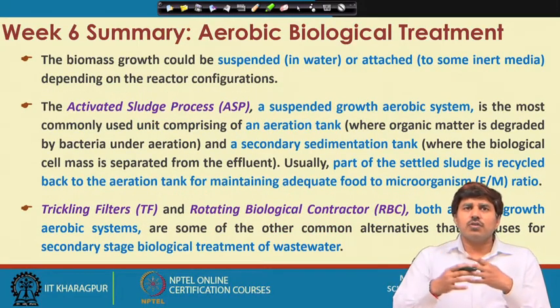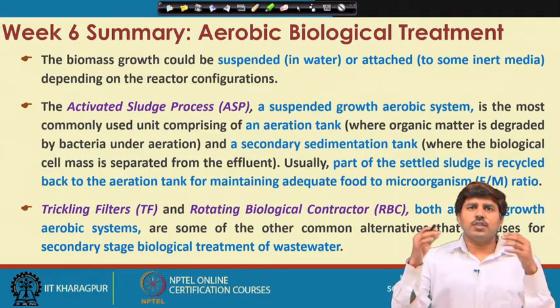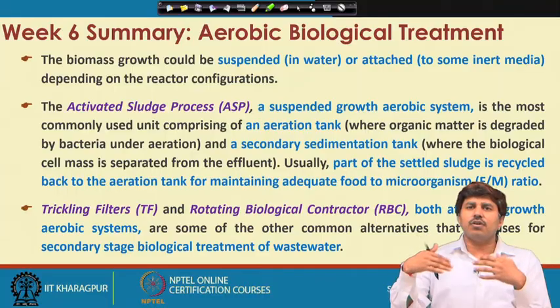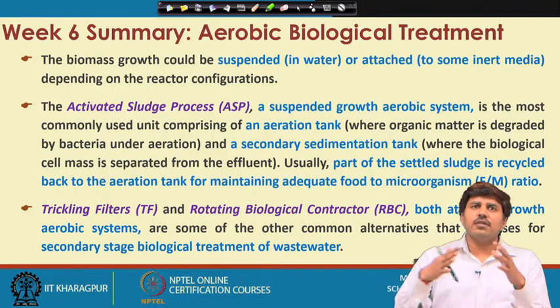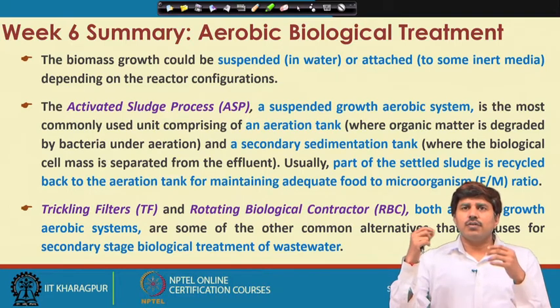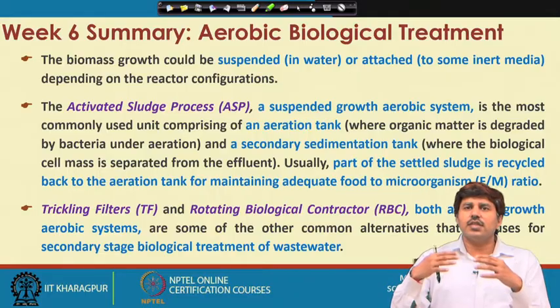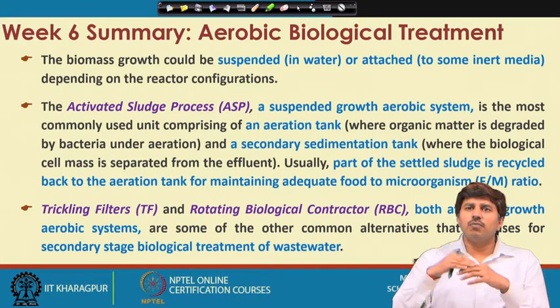The biomass growth could be suspended or attached. The suspended growth are where the microorganisms remain in suspension within the water, whereas in attached growth systems they grow on the surface of some media. So, some inert media is provided, and on the surface of this media the biomass grows slowly and as a result forms the biofilm.